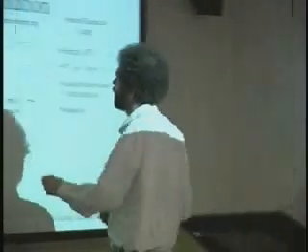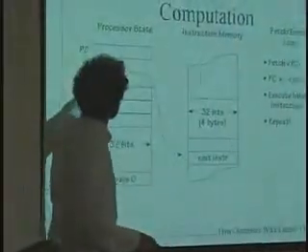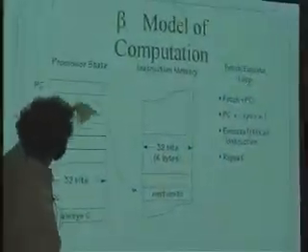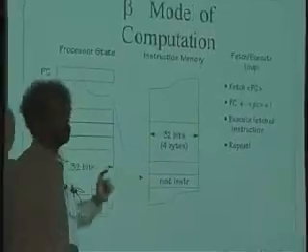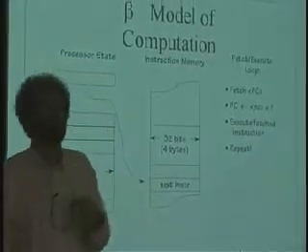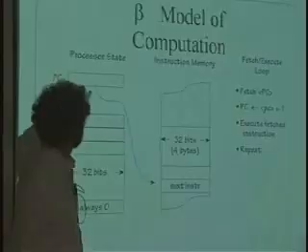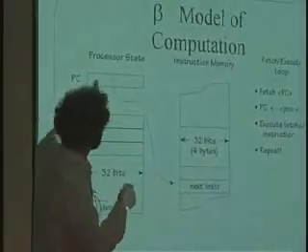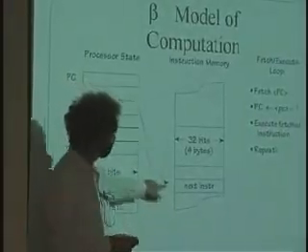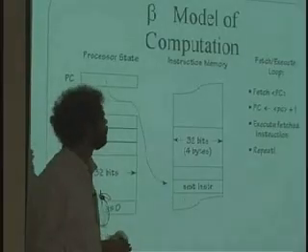So we talked about there being a program counter. That's this storage right here. And that's going to point into the memory system. And it will always point to where the next instruction is that we're going to do. So the PC is a value itself 32 bits wide. And it's going to point to where we get the next opcode from.